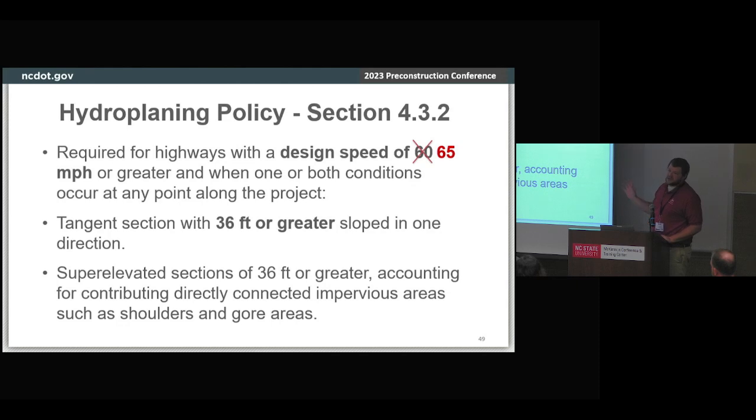We've done so many assessments now that we can safely confirm that when you're at 60 miles per hour, you're not going to have an issue at a design speed, unless you're over, I think it was 110 feet of a wide typical. So if you're seeing something over 110 feet, then maybe it will apply. But we're going to update that to 65 for the most part, and we may have that addendum in there mentioning the width. Okay?